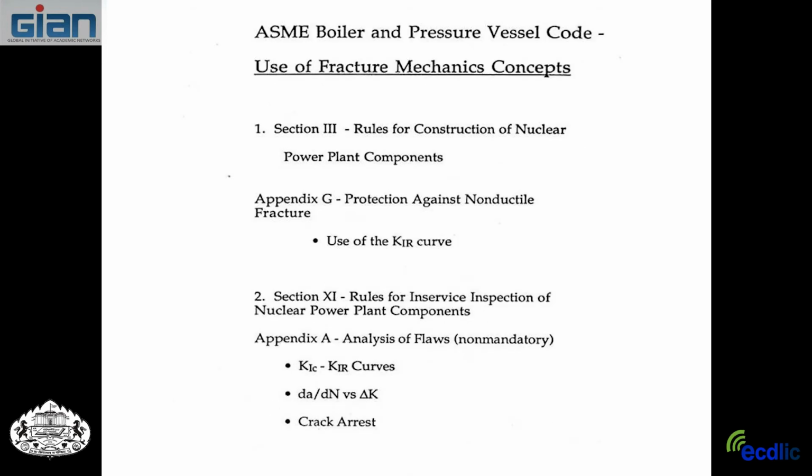Some of the ways that things are being used is in the ASME boiler and pressure vessel code. They use fracture mechanics in several things, mostly related to nuclear power plants. Section 3, Appendix G uses it. Section 11 uses it in this way.